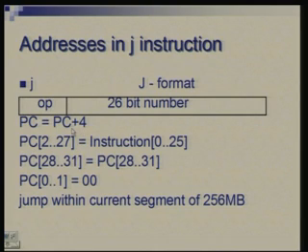Although we are not going to the next instruction, but this happens automatically. This happens in terms of hardware, PC gets PC plus 4 without even bothering whether it is a jump instruction or a branch instruction or something else, and after that we see how rest of the address is computed.